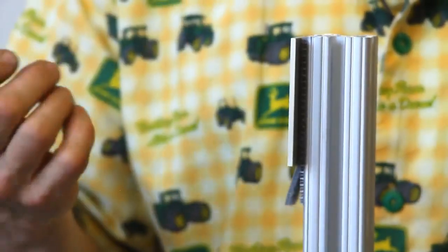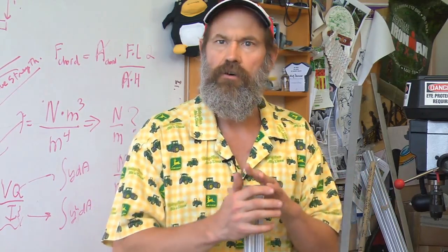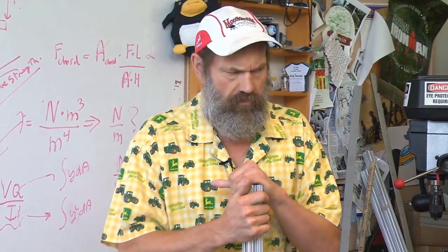Okay, so remember that this is a very powerful trick when you're thinking about adding plates to structures to your machine, whether it's a cosmetic or a safety effect that you need to add coverings, that you can often get higher strength out of your machine for less cost and less weight by having the coverings or closures become part of the structure when they're closed. Hey, wait a minute.